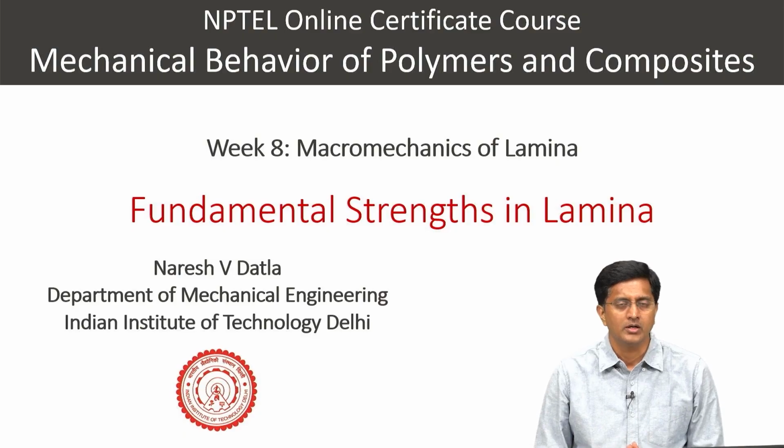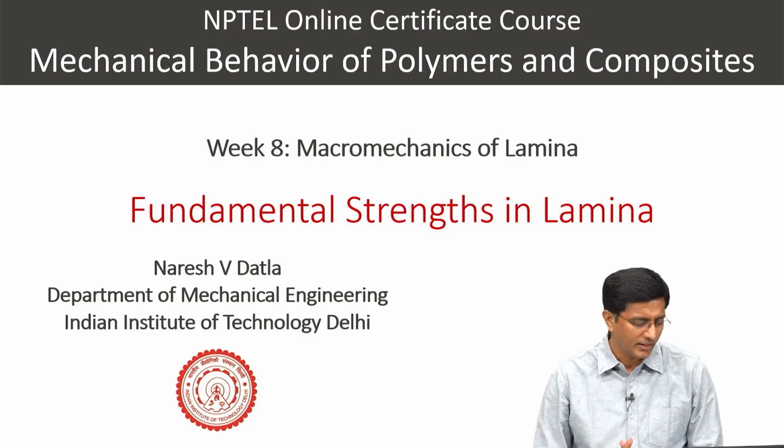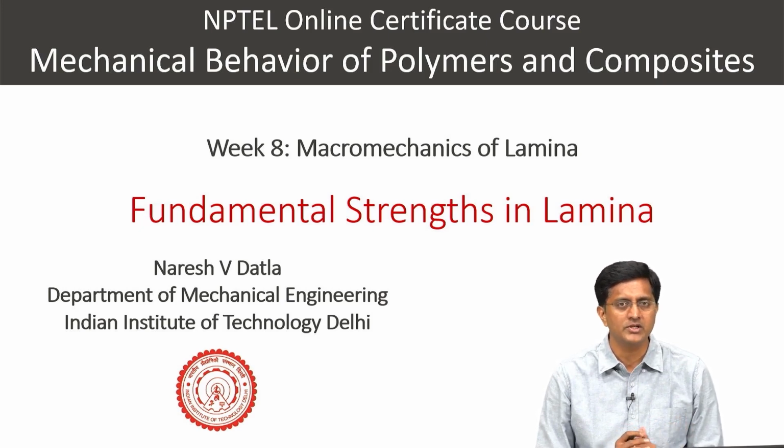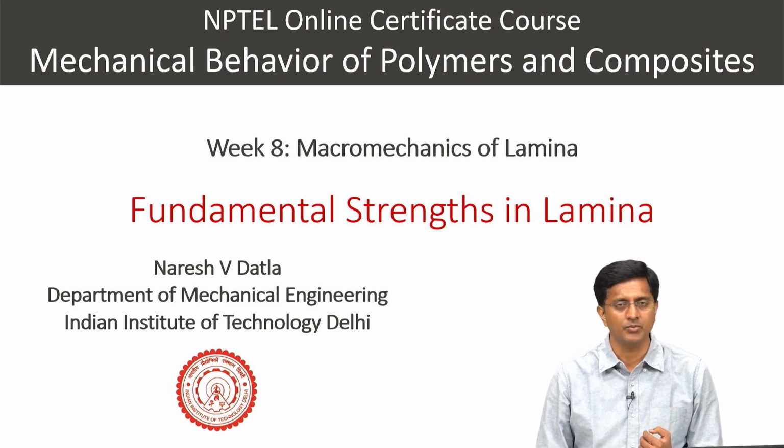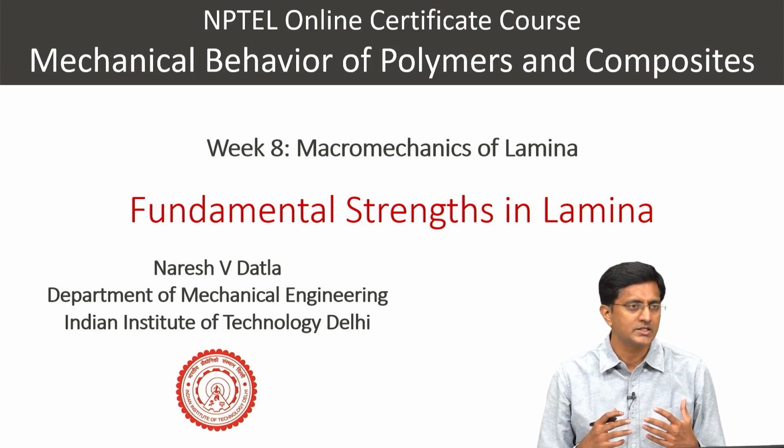Hello all. In this video we'll be looking at the strength properties of a lamina. Until now we have been looking at the stiffness of the lamina, where we have looked at the stress and strain relations. But strength is also equally important, especially when we want to design these composites using the lamina. Meaning we want to know when this lamina fails when we design.